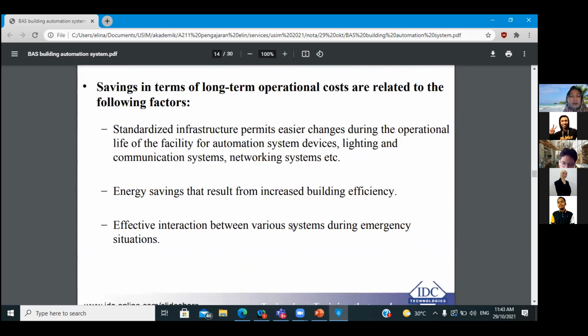On the energy saving result, sometimes you are using very much aircon, but at the same time the architect simply proposes glass on all four sides of the facade, without trying to understand the orientation. Sometimes on the west facade you also provide a lot of glazing. What for?